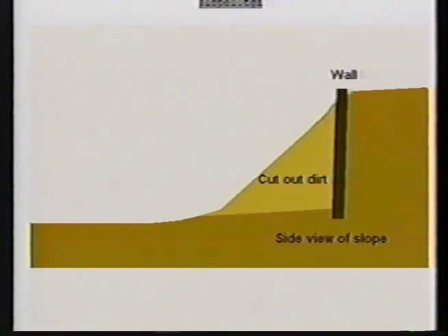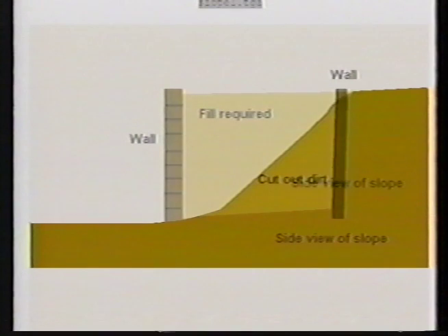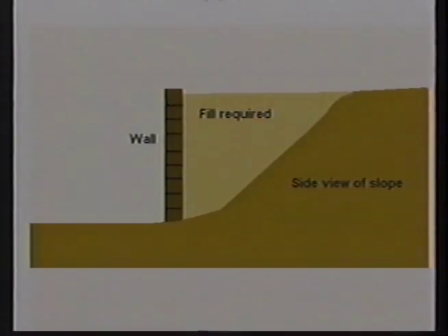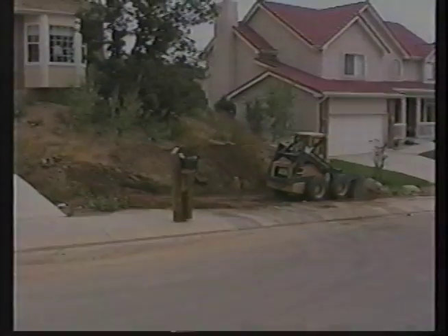If you need to excavate or cut into the hill, now's the time to do it. If you're going to build the wall on grade and fill behind it, determine the amount of fill needed by multiplying length times width times average depth to obtain cubic feet of fill required. You may want to consider renting a small skid loader to reduce the amount of hand digging necessary.